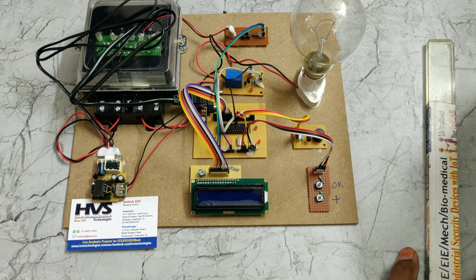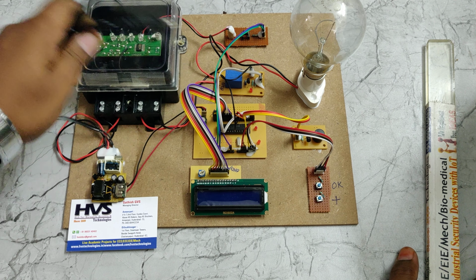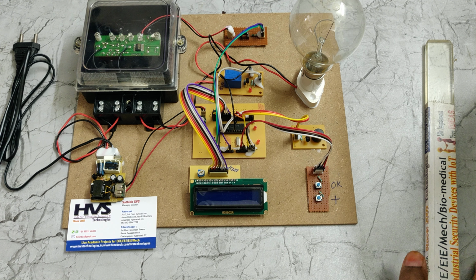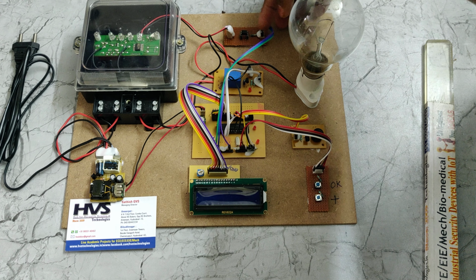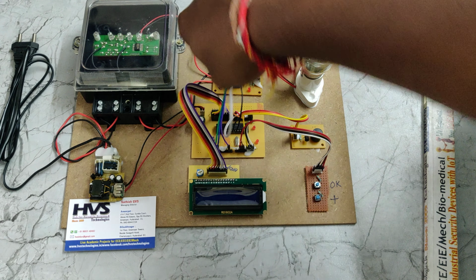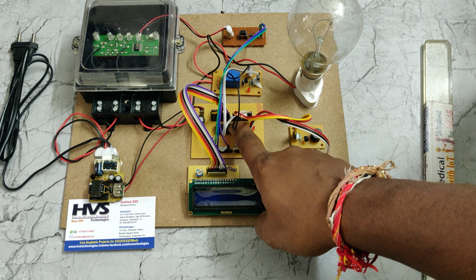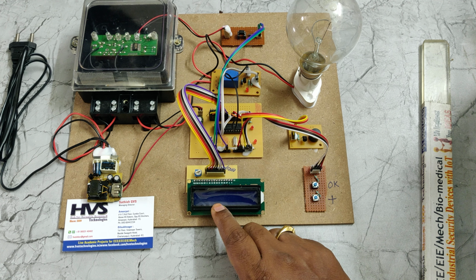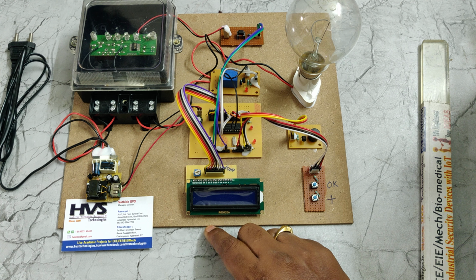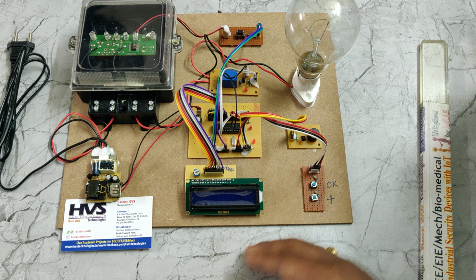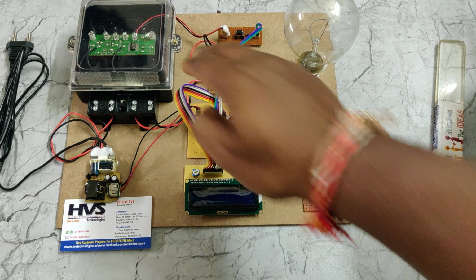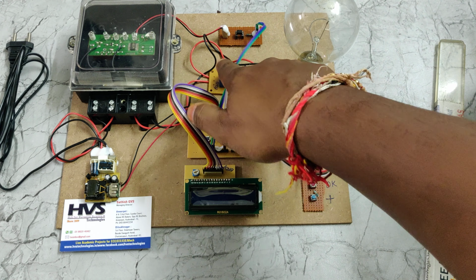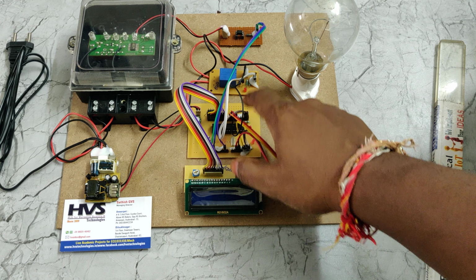For that purpose, we are going to use this energy meter, which will continuously measure the wattage of the particular load connected to it. The energy meter reading will be continuously read by this PC817 optocoupler IC, and the output is input to the PIC16F72 microcontroller at the A4 pin, and the project status will be displayed on the LCD screen. We have interfaced it at pin B2 to pin B7. Based on the limit being crossed, when the threshold value is crossed, this electromagnetic relay isolates the power supply to the output load, and it is connected at pin C7 of our microcontroller.